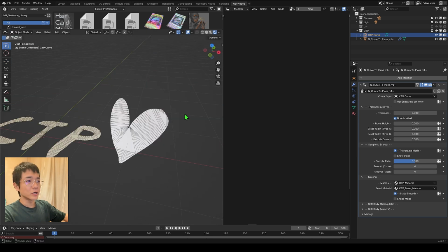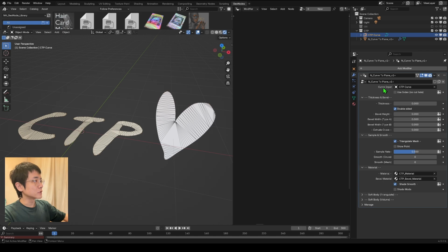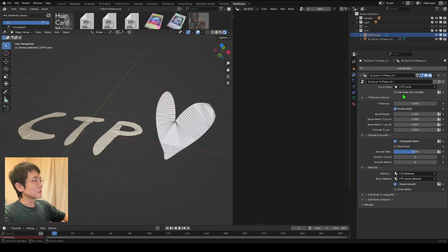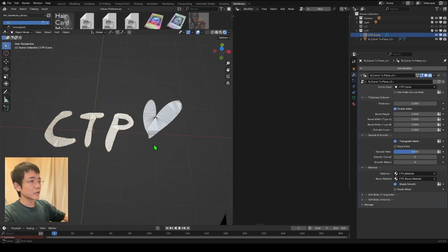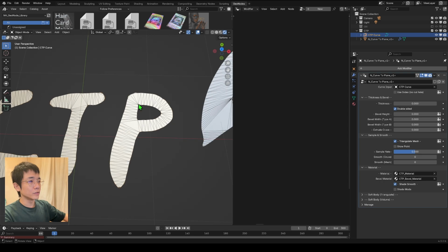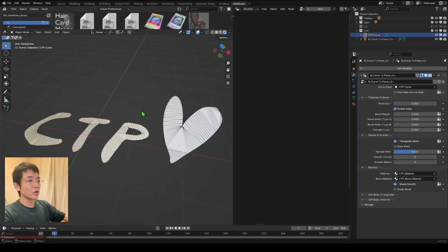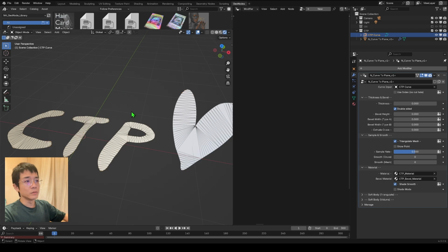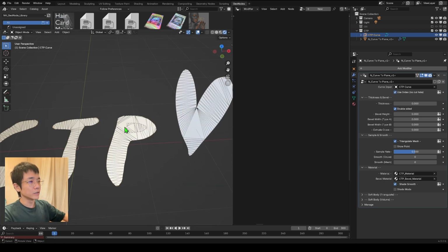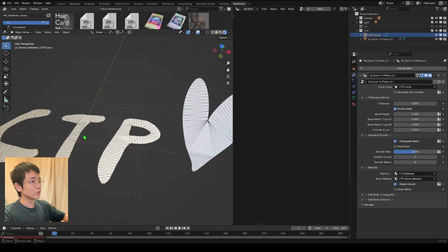Now let's go check on what the node does. So the first is curve input. So you just pick any curve. The second one is the use index. So as I said, if you are not using index, you can cut the hole within the plane, but sometimes it will give you some bugs if you draw multiple curves. Sometimes you need to click on this, but it will not make any hole. You use this when you need it.